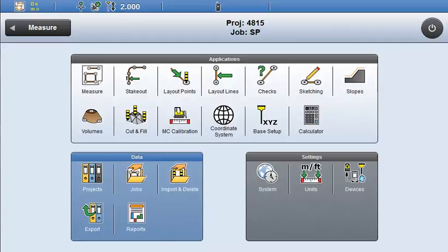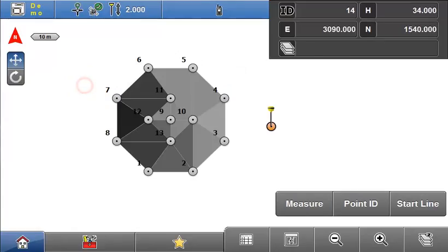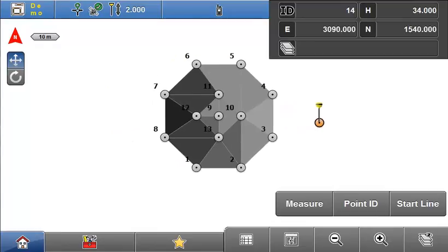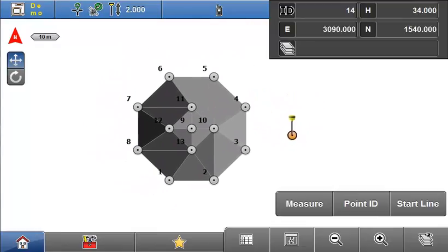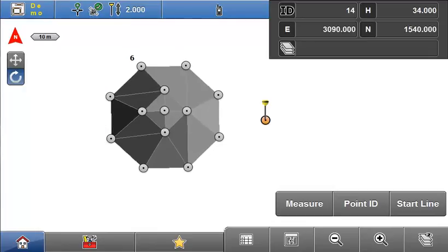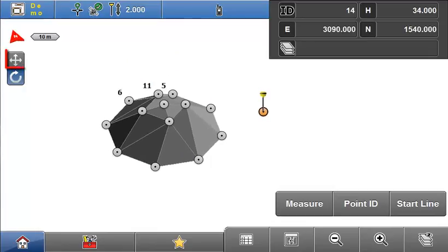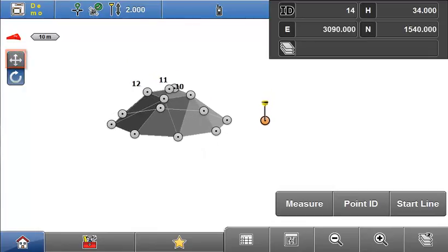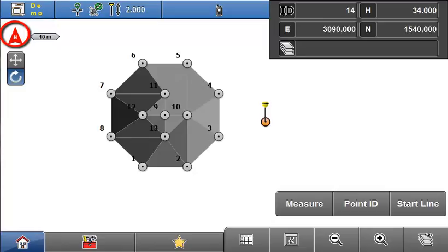3D view is available within any map application except for Sketch and allows the user to continuously check objects from any desired angles. In this case, a surveyor has measured a stockpile by taking spot levels and a surface has been created from them. The panning and rotation is distinguished by toggling the desired button from the map view, and resetting the position to default orthogonal view is done by clicking on the north indicator.